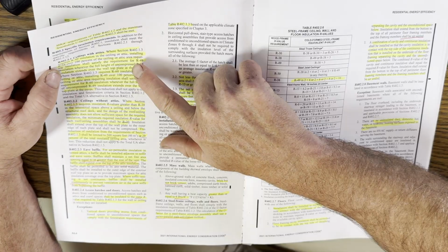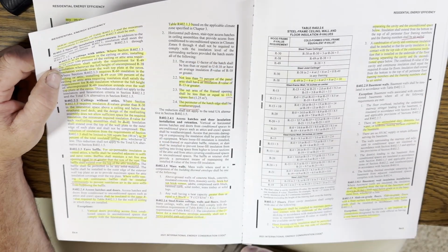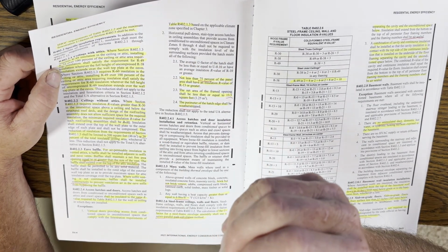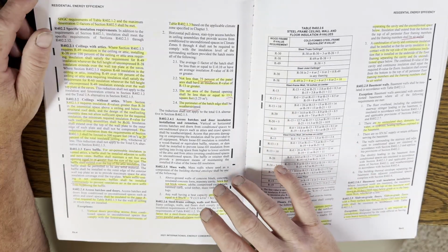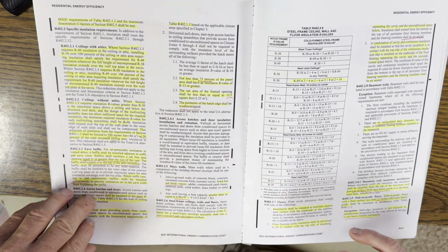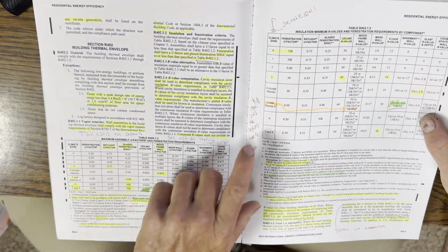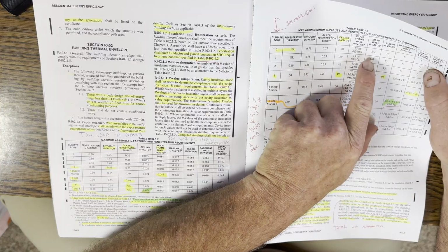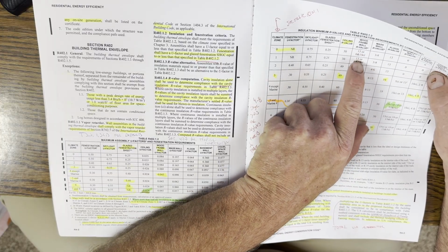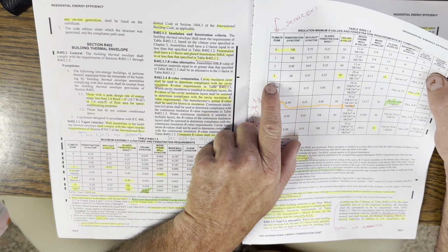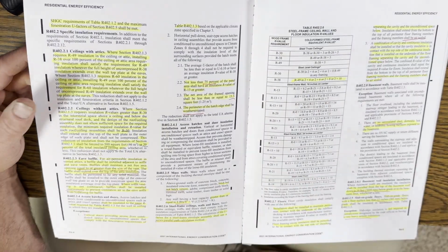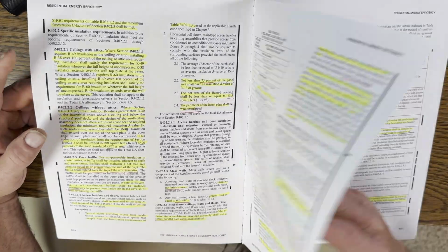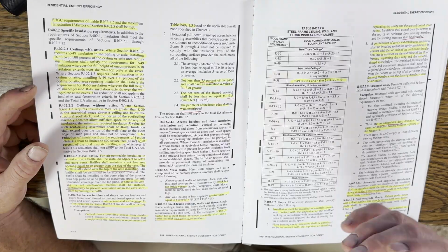Ceilings with attics. I had a question about a penetration through a ventilated attic for a skylight. What does that penetration, that wall, look like? I put down that the insulation on that wall is the same as wall insulation here, wood frame wall R value, I think climate zone 3 or something. So it gave you one of those options. There's actually a statement about that somewhere. But the point is, you're going to treat that penetration the same as you would a standard wall.